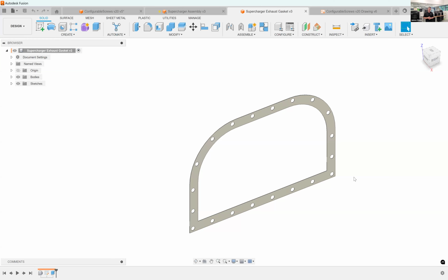If it is an assembly, the first sheet will also be an assembly sheet. So it'll just be some isometric views of the assembly as a whole. It won't break down that list, and it will have a parts list there, and it will also have balloons to go with it. So it's not about completing your drawing for you. It's about doing a lot of the tedious work for you: creating the sheets, the repetitive base view placing, and so on.